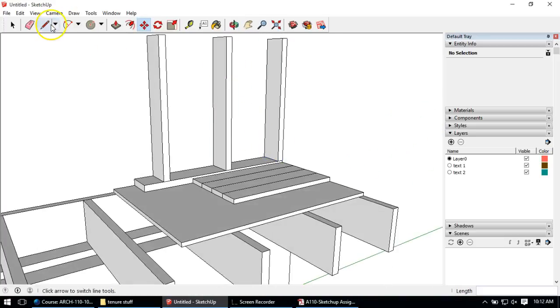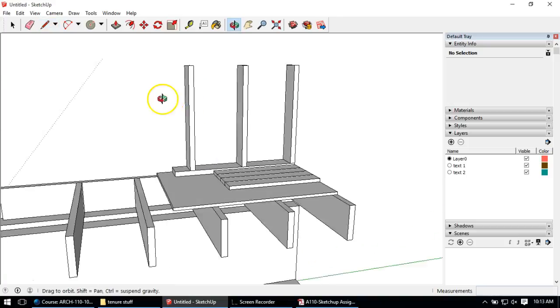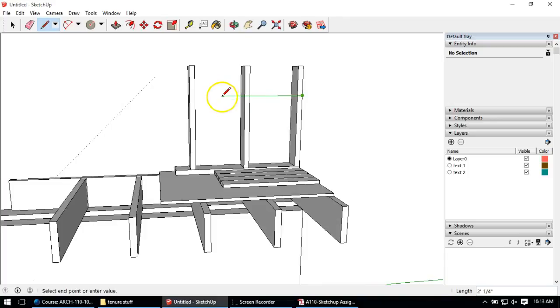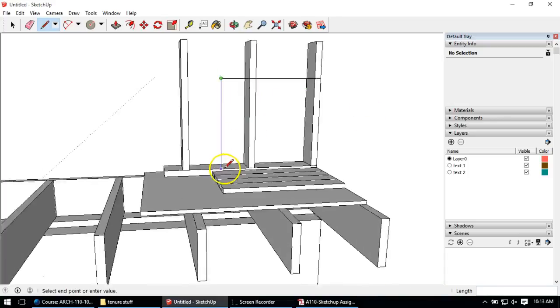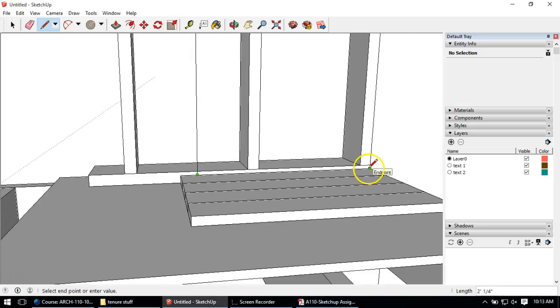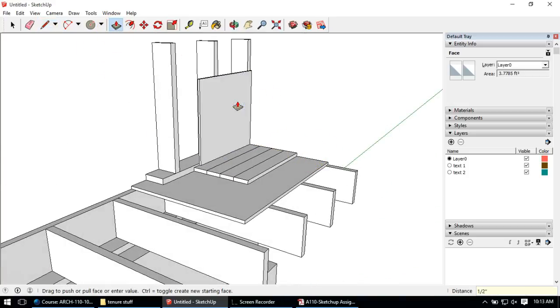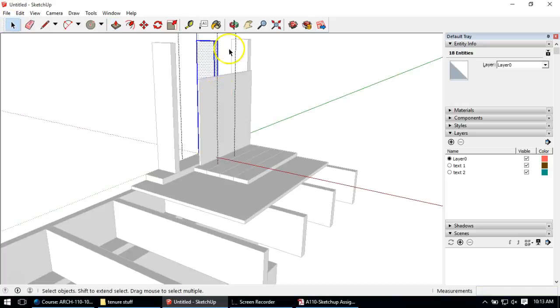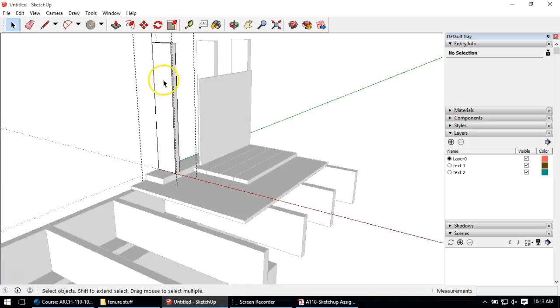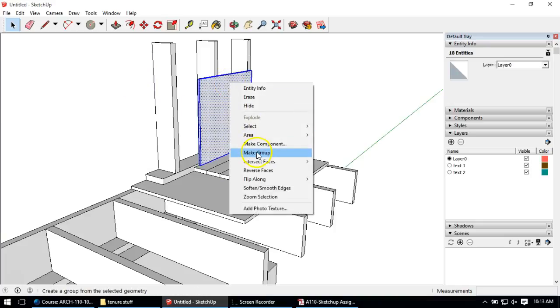Now I'm going to do the drywall, because I can sit this on top of the floor. So I want to snap from that corner. I'm going to go up approximately 3/4. In the drawing, this drywall is back shy of the wood a little bit, so I'm just going to sort of visually, again, do it, making sure I had that green line. I'm going to come down all the way down to the top of the floor, not the top of the stud, top of the floor, and come over here, close the object, and I'm going to pull this guy out this way a 1/2 inch for the drywall. Whoops! I triple click. I click to get the group, and to enter a group, if I need to edit, it sort of entered the group. I see the black dots. I didn't mean to do that. I meant to triple click on the drywall and right click and make that a group.